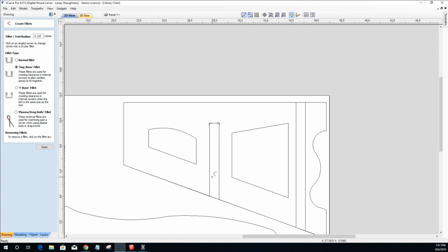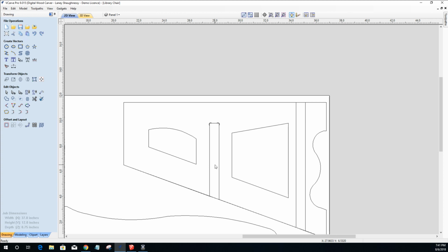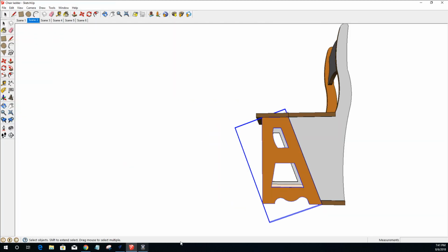But that shelf vector is an important part of the structure and the use of the ladder. That's one of the steps. So whatever we change these two designs to, if we did some kind of ornate carving where it's not carved through, where it's not a through hole, or if we stuck with just a basic design like you see here, these two vectors would get profile cut all the way through. They're going to be separated, so we wouldn't be able to do one long design because we have a shelf pocket in here.